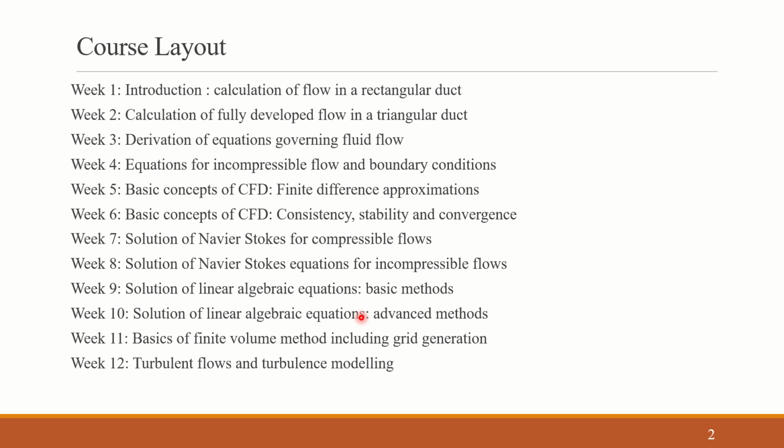So basically, what our understanding is from the last class is that CFD is nothing but getting the solution of the fluid flow in a system by means of solving equations. If it is a simple flow, where only water or any single fluid is flowing, we have to deal with only two equations. One is the continuity equation, the other one is the Navier-Stokes equation or the momentum conservation equation.